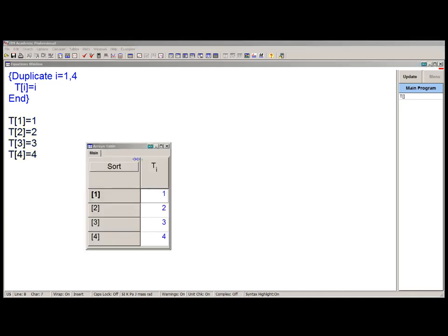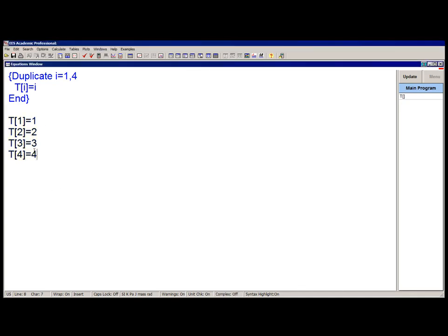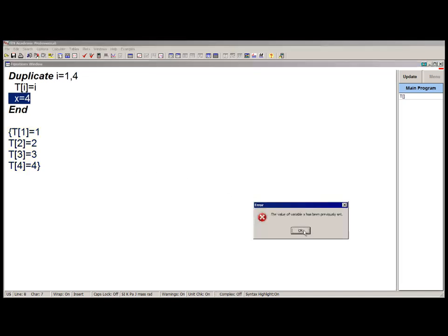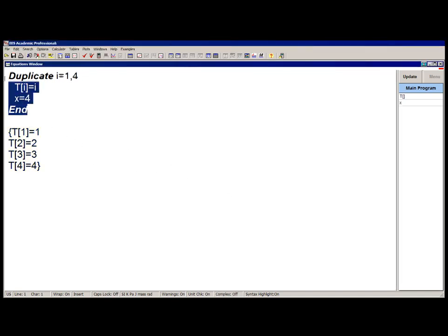When you're using duplicate statements, it's really important that you remember that EASE is an equation solver and not a programming language. So don't accidentally place equations within a duplicate statement unless you want them to be actually duplicated in the equations window. A common mistake that some users of EASE might make is shown here. So this looks okay, but it's actually exactly equal to writing the EASE code that's shown here.